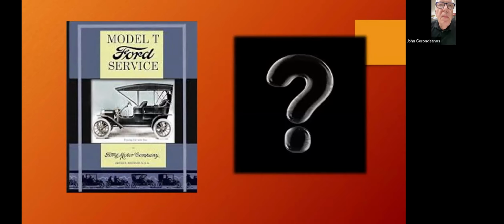So Ford's recommendation is that it picks up a Model T piston, and that is 2.2 pounds. Anyway, that's what I did, and it seems to have worked quite well. So definitely a method of magnetizing the coils would be to wind the coil directly onto the magnet, and ideally you would put a keeper across the front to complete the circuit.